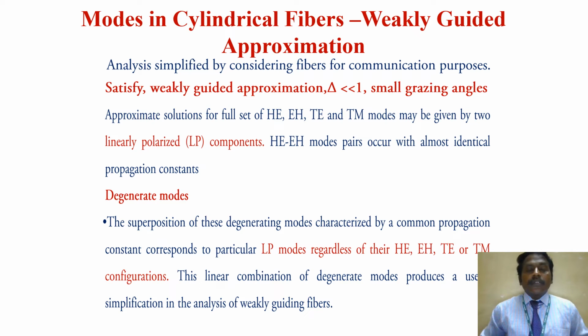So then we are going to discuss the modes in cylindrical fiber. The modes in cylindrical fiber we are going to define based on the weakly guided approximation. So the analysis is simplified by considering the fibers for communication purposes, where the guiding approximation applies, where del is less than 1. So we know that del is the index profile parameter. If it is less than 1, that is small grazing angles, then the approximate solution for the entire set of EH, HE, TE and TM modes may be given by two components called linearly polarized components.